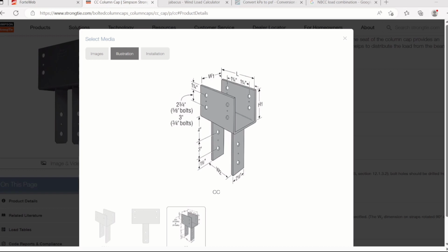And then we haven't done the vestibule part. So we will do the vestibule also, considering the snow drift, assuming that the downspout is not discharging onto your vestibule, then we can say that the governing load on that one is the snow drift, which is really high at the vestibule location. And then next would be the diaphragm and shear wall design.